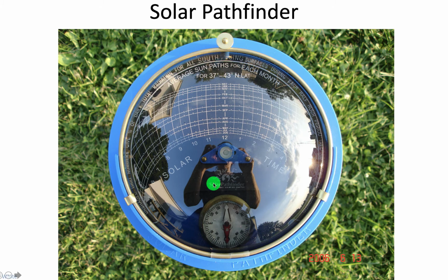And since this is using a magnetic compass, you would also adjust it for magnetic declination. This will spin. You spin it counterclockwise if you're on the western part of the United States, and you spin it clockwise if you're on the eastern part of North America. If you're in the middle, say on the Mississippi, you don't have to spin it at all.